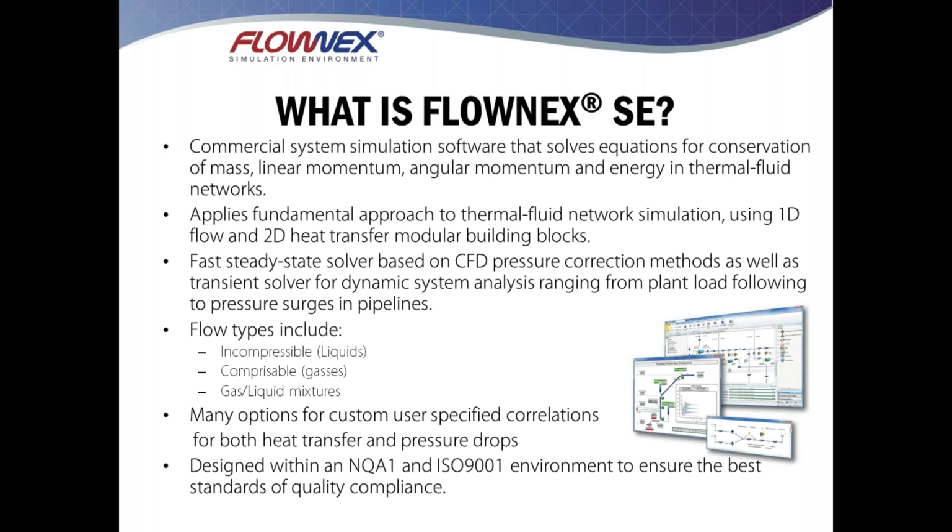Flownex has a lot of built-in fluids. These include incompressible fluids such as liquids for modeling cooling or lubrication systems, as well as fuel supply systems for turbomachinery. We have compressible models for modeling your primary flow as well as any secondary flows, and can also include mixtures of gases or gases and liquids for the purposes of modeling combustion or combustion products.